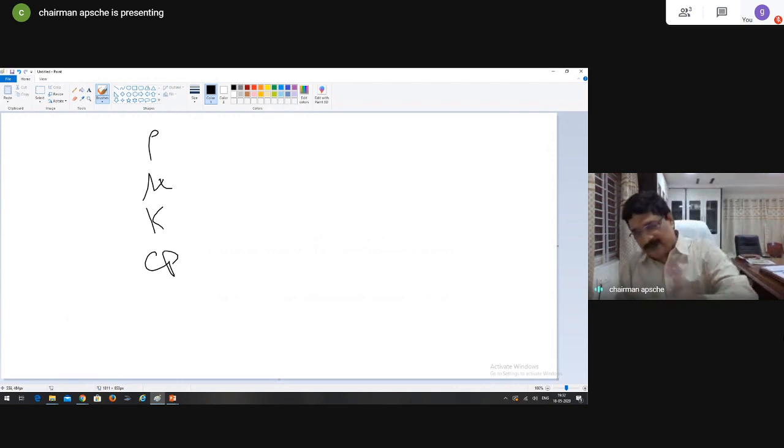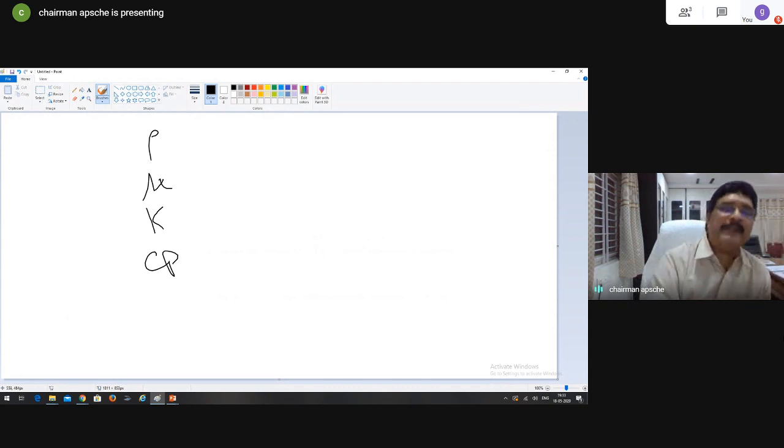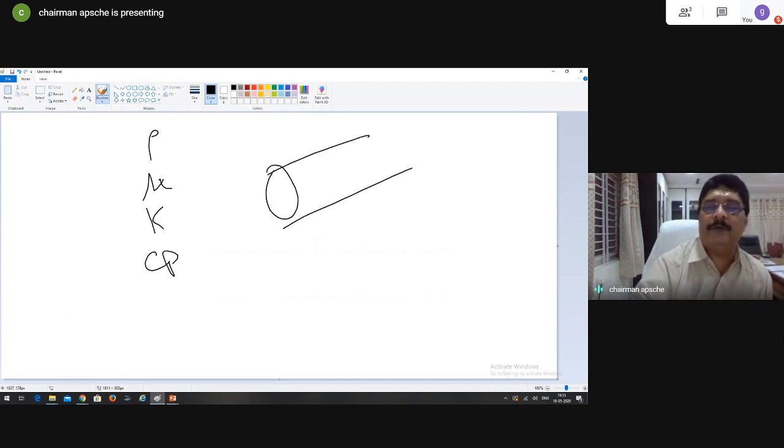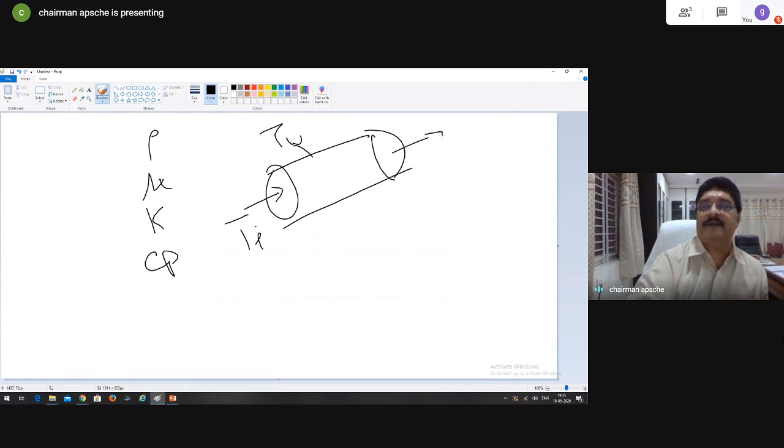Certain times, for all these gases, the data book straight gives you the Prandtl number. In such a case, you don't need Cp. So the properties, where do you estimate? In this kind of pipe flow, you will have three temperatures. One is the wall temperature given for the pipe, the entrance temperature Ti, and the exit temperature T0.